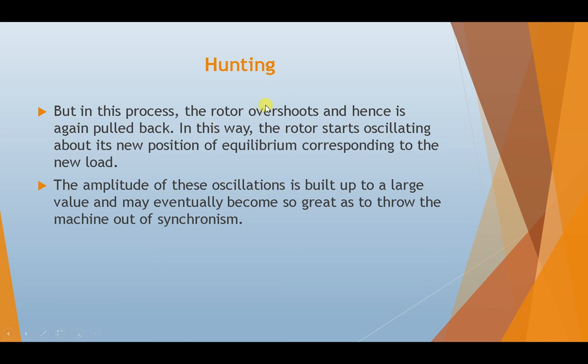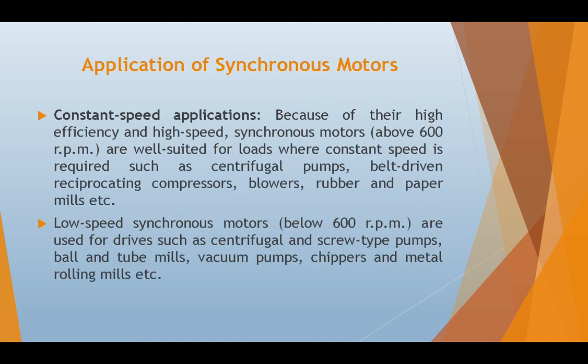So hunting is a process in the machine, and due to this it throws the machine out of synchronism because of an increase or decrease in load.